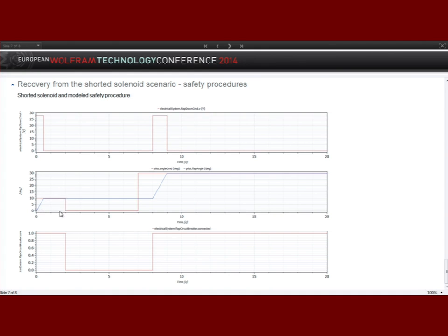And exactly as before, there will be a problem. It will not get from 10 to 0 degrees. It will not go from 10 to 20 either. But it will actually be possible to switch it to 30 degrees. So suddenly he has a safe way to land. And the combination now of the hydraulic library with Mathematica makes it possible to build this system, build different failure scenarios, and then programmatically go through in Mathematica to identify what is it I'm failing with and how could I prevent it from failing.